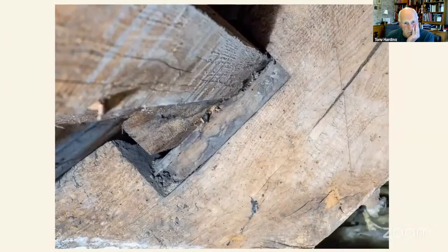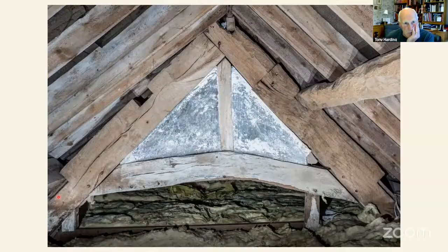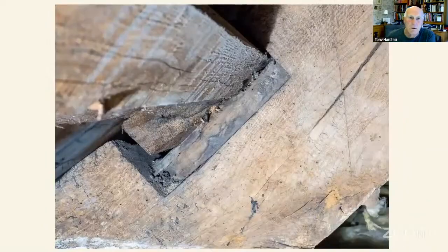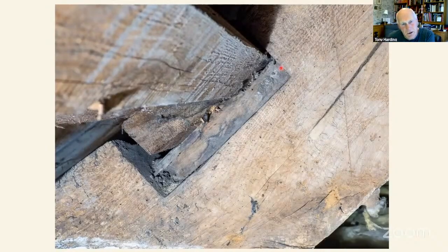Some I can't. This little purlin trench down here, there's something that looks a bit interesting about that, but you can't really see it from a crop of that. So here I've had to reposition my camera and my lights, get down there and whisk out some dust with my Hoover, and get some light in there. And you can now see it's an interesting joint. It's like a trench, but it's got this sort of locking rib in the middle, which is a little bit unusual, but it's to stop the purlin sliding when it's in that joint. So interesting bit of detail, characterizing that carpentry.